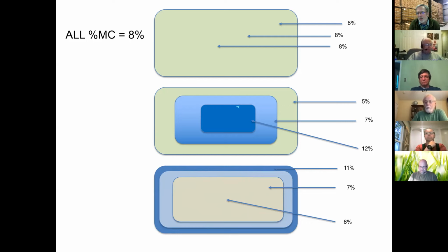And this is actually a common problem even in the industry. If you store wood just under a roof or in a shed with the doors open in the summertime, I've seen red oak pick up as much as 11% a quarter inch in from the surface of a piece of lumber. So it does happen, and this is another example of a gradient where it can cause problems for you. If I produced a piece out of this, ripped it into pieces and then glued it into a panel, anything that contained lumber from this piece is going to shrink and move on me as it's glued into the panel.